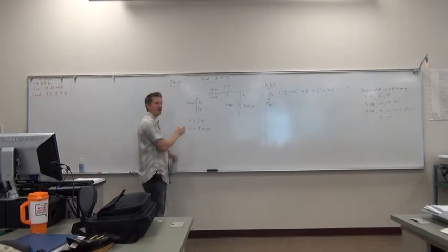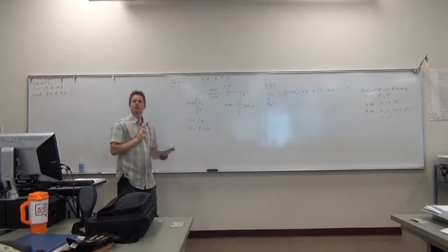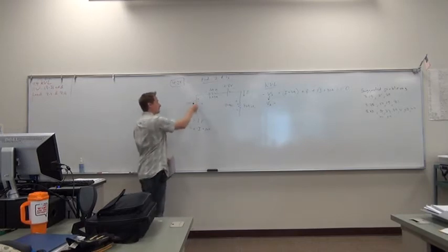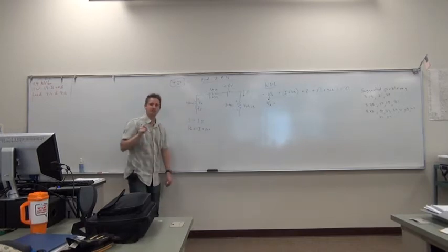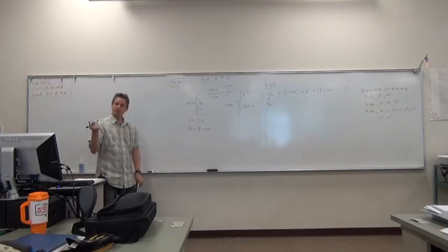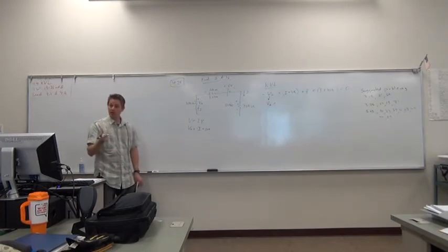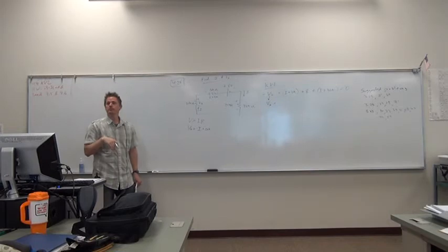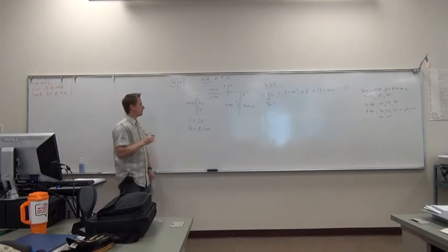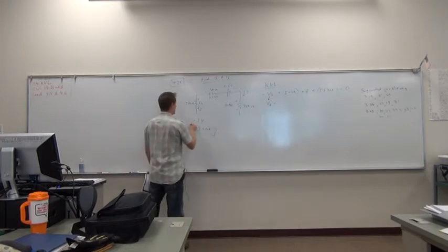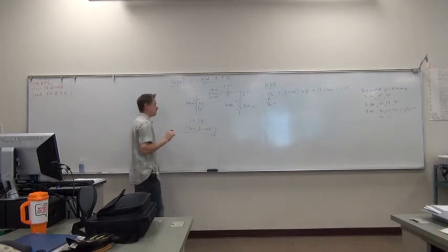So you have to add a minus when you use Ohm's law. If your reference voltages and currents are passive, then you use a plus for Ohm's law. If it's not, then you use a minus. So Vx is equal to minus I times 20K.